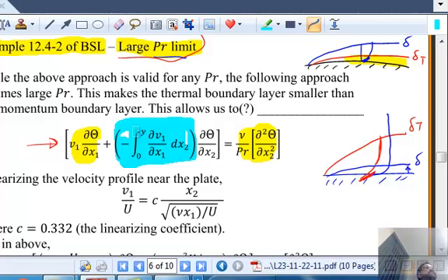The continuity equation. Okay, so basically I took the continuity equation, separated the two terms, and integrated it once. We have used this idea once before, in the momentum integral analysis, when we are trying to eliminate V2 using the continuity equation. So that is a continuity equation that replaces V2. So I have only V1 and its derivatives.